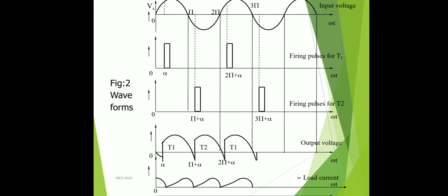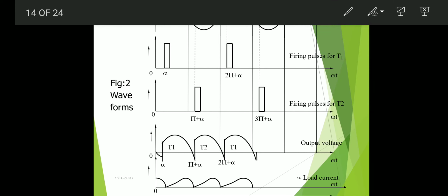See, this inductive load is similar to the half wave controlled rectifier with the RL load. The only difference is that here the conversion is for 2 cycles. That is the reason we are getting the positive voltage with a small negative and immediately positive output voltages, and here the current is almost continuous but with zero values. This depends on the inductance value.